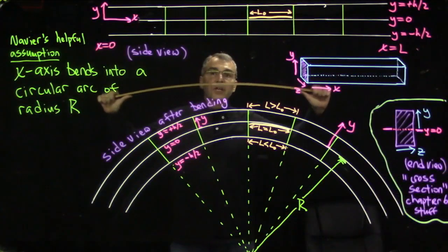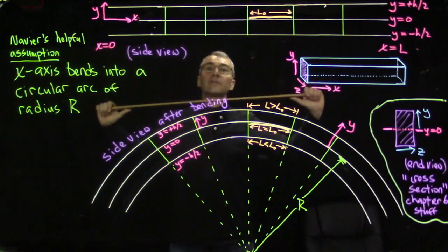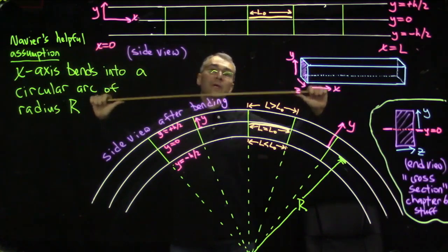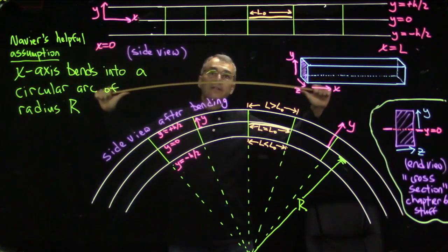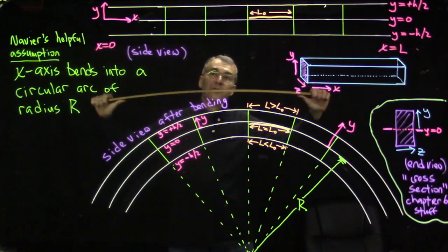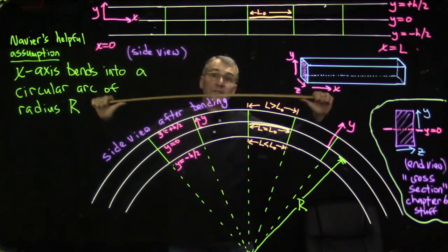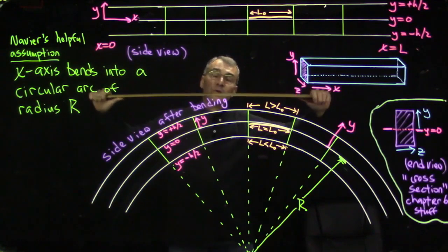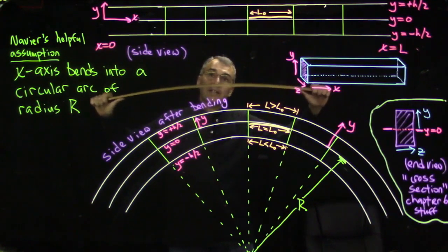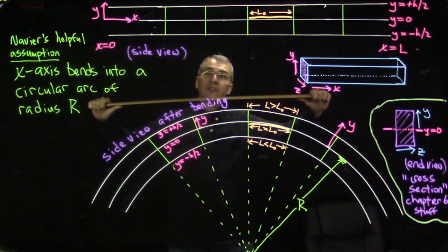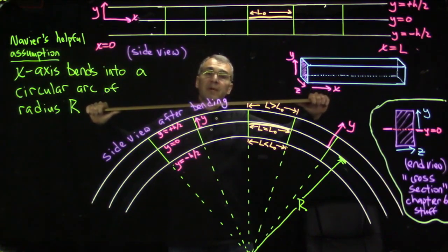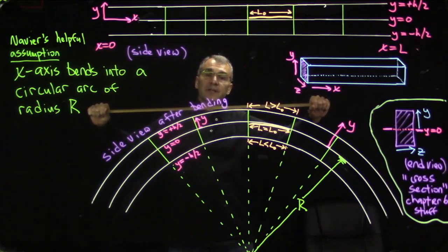We want to relate the shape of a beam when it bends under load to the strain and the stress in the fibers that we imagine constitute a beam, that really do constitute a wooden beam, and that we sort of imagine are there for the purposes of envisioning stress and strain in other materials. And we want to relate those internal stresses to the bending moment and the shear force that we drew as V and M diagrams last time.